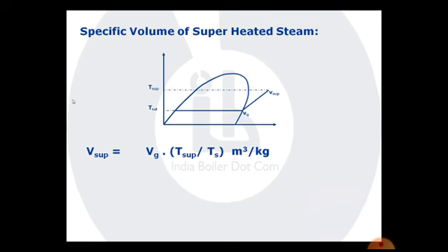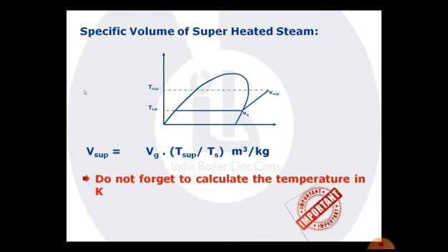One thing we'll have to remember, we are using the gas laws, therefore do not forget to convert the temperature to Kelvin. If you do not do that, you are going to get a wrong value of this. Okay, so this is how the specific volume is calculated.